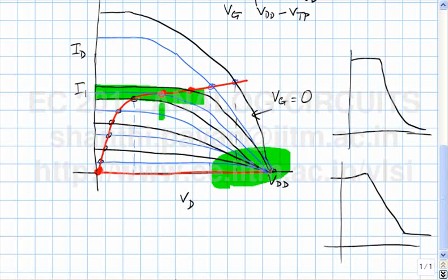If you gave me a digital logic gate, a NOT gate, I will be able to use it as an inverting amplifier. So next time when you come to the lab, you will see this happen. We will take an IC which has got 6 NOT gates in it, which are all CMOS inverters. This is a chip which is commonly used by a lot of digital folks. Okay, it's got 6 NOT gates on it. Okay, and a CMOS inverter, a NOT gate, is as digital as anything can get.